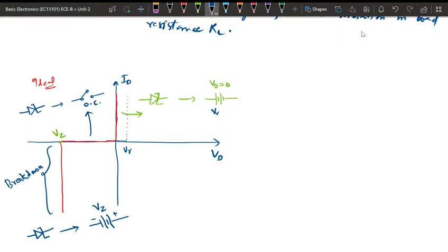in further analysis also. If it is used anywhere in a circuit, you can just replace it if the Zener diode is ideal. In the forward region, it will be replaced by just a short circuit, you can say 0 voltage, or if it has some cutoff voltage or knee voltage, then a voltage source will be used. Otherwise it will be a constant 0 voltage once it is on, or we can call it a short circuit in case of the forward region.